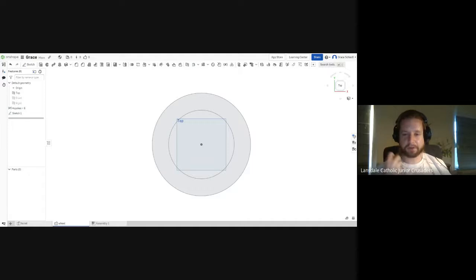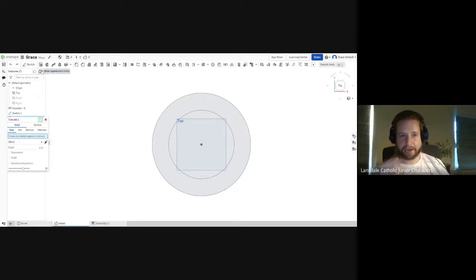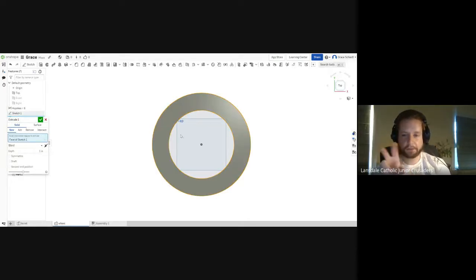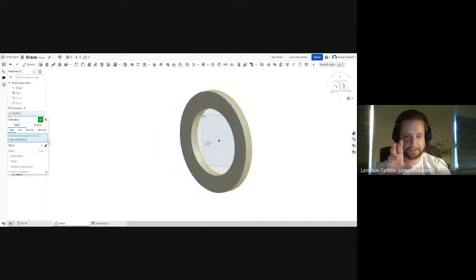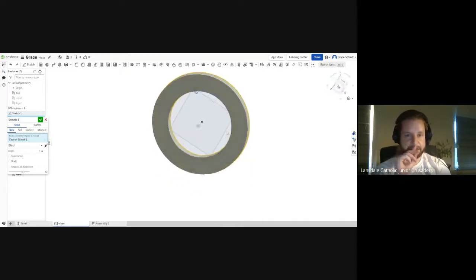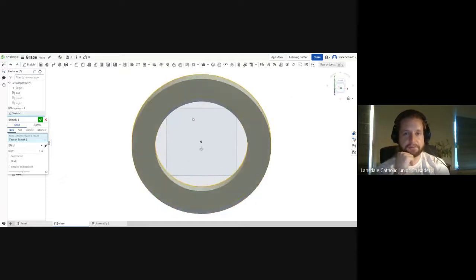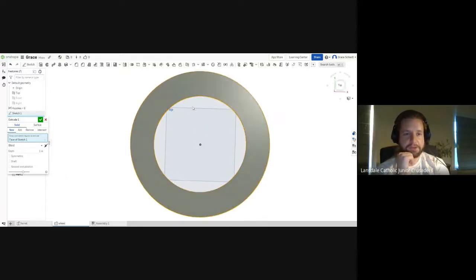And I'm going to have you bring this into 3D, so you're going to use the extrude function. That's okay, right? Yep. So just use that, and just select the outer ring. You're in the selection box right now for what you want to extrude. That's what's blue highlighted there. So just click the outer ring. There you go. And now if you rotate around, you'll see that it's got some thickness to it now. And if that looks like reasonable thickness to you for a ship steering wheel, then you can click the green checkbox or adjust the number.